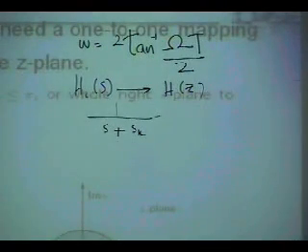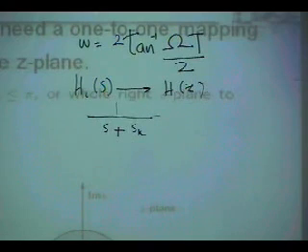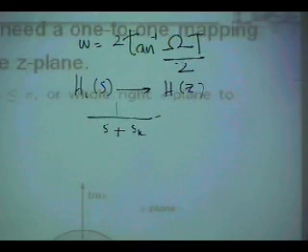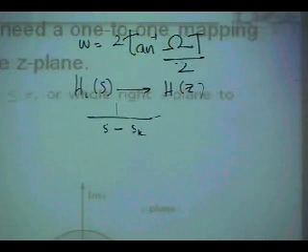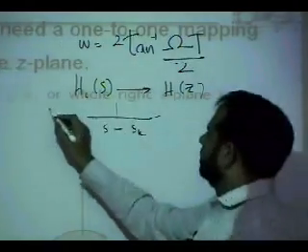This is a single pole system. And sk is, in this case, I think negative may be appropriate. sk is the pole, it should be negative, because once you put it equal to 0, s is equal to sk, and sk must have negative sigma. So this is Hc of s.